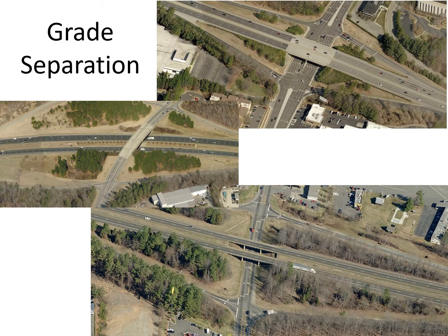So starting with grade separations, that's the next level you would go to. Obviously this works well to avoid those left turns. If you're on this facility, in these examples, interstates, freeway access control facilities, you do not allow a direct left turn to cross the other direction. So to do that, we grade separate them, you exit, and then you make your left turn over or under that main line.